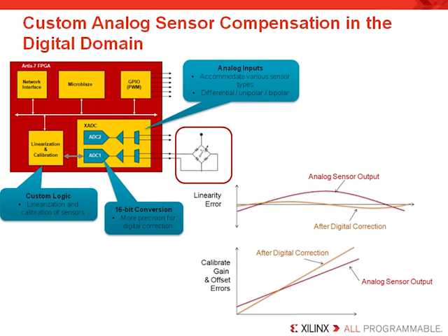However, the ADCs carry out a full 16-bit conversion. It still complies with a 12-bit specification, which significantly reduces the quantization error or noise. The additional 4 bits of precision can be used to improve resolution through averaging or filtering. To linearize a sensor transfer function, one approach might be to use an interpolated lookup table in the form of a single 1K by 18 block RAM.